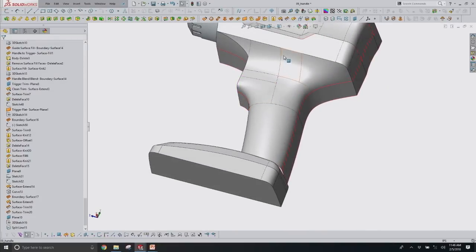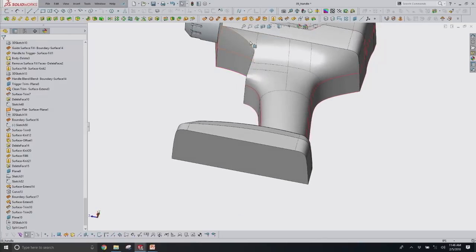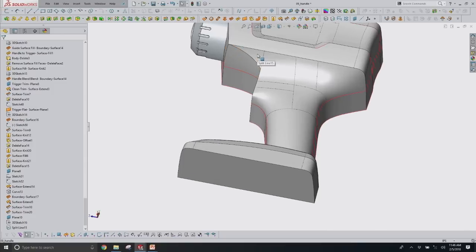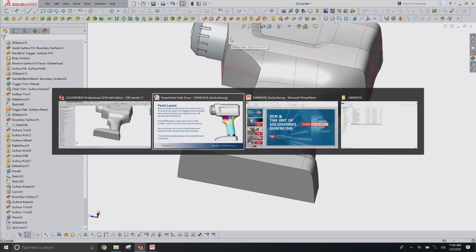To complete this tricky portion of the transition, I created a boundary surface larger than I needed to, and then I trimmed it back, and then I created that surface fill to get me out of trouble. Likewise, big boundary surface here, and then that three-sided patch is happily and easily conquered with the surface fill tool to create that larger patch, trim it back such that I don't have that degenerate point, which could really screw up the situation when I start adding fillets in this region.